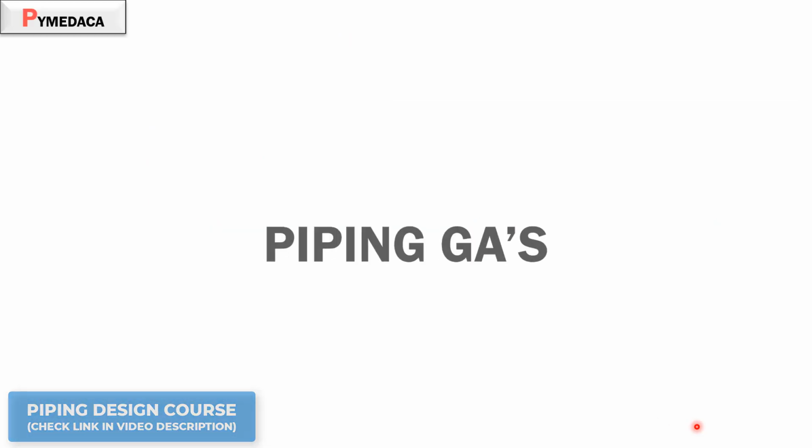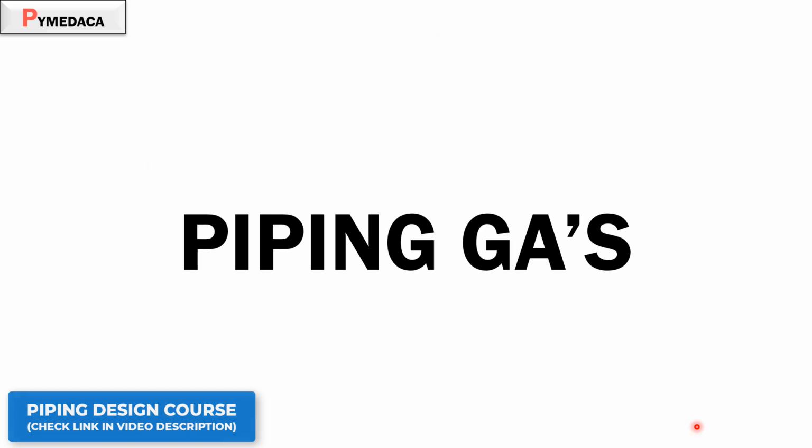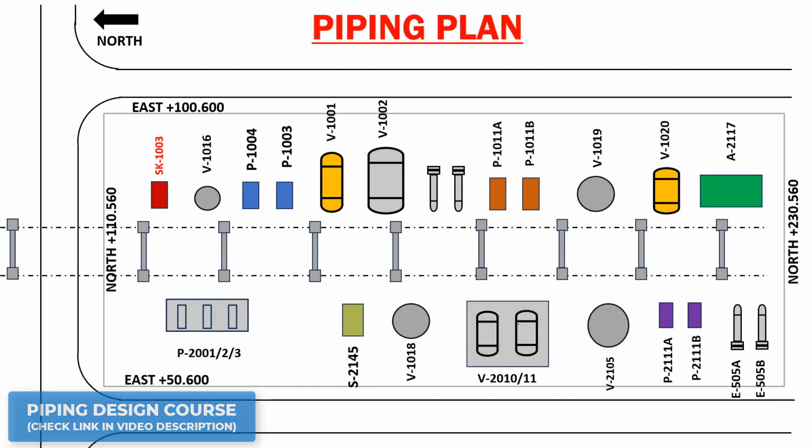So what next? The next is that you have to pull out the respective piping GAs. Piping GAs are nothing but piping arrangement drawings basically. You have to take the respective piping GAs, and only then will you be able to finally develop the piping design. Now let's imagine the piping. This is the piping GA. See, if you pull out the piping GAs, you will be able to understand the pipe routing.